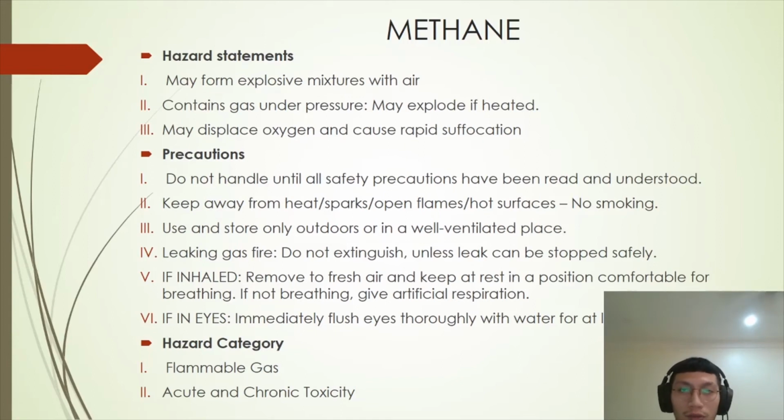Okay, if methane is inhaled, we have to remove to fresh air and keep at rest in a position comfortable for breathing. If not breathing, give artificial respiration. Okay, besides that, if contact with eyes, immediately flush eyes thoroughly with water for at least 15 minutes. Hold the eyelid open and away from the eyeball to ensure that all surfaces are flushed thoroughly.